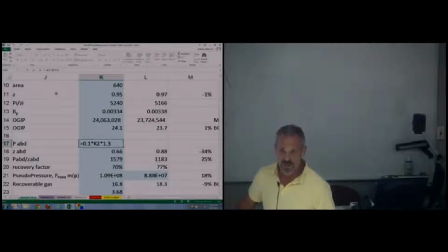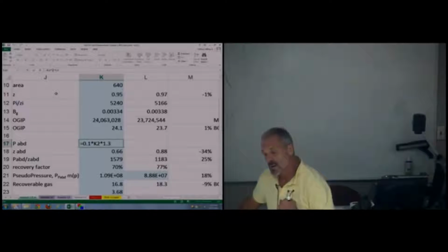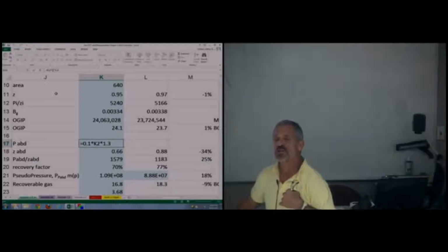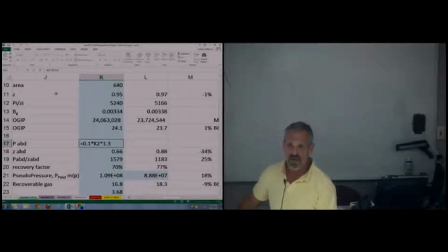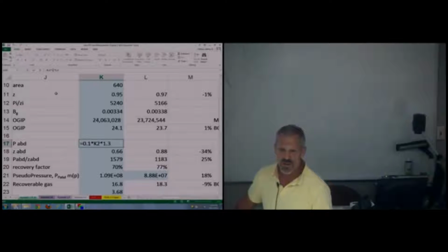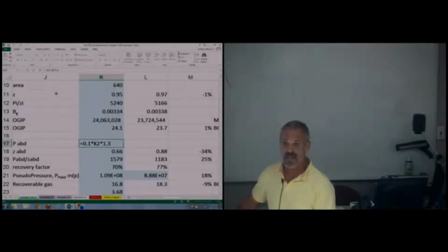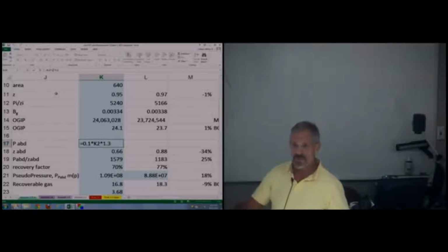We have all kinds of logs we run in the hole, and it depends upon what formation we're interested in producing, which suite of logs best applies for the information that we need. But every single log that runs in the hole has a temperature gauge. And it needs that temperature because when it displays its output, they're all temperature corrected, just like we have to make temperature corrections. So on the cover of any log, how many people have seen a log?